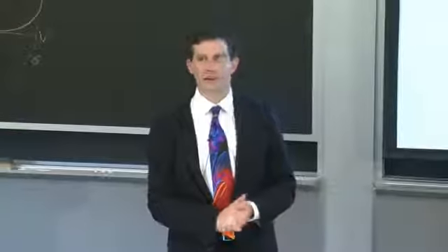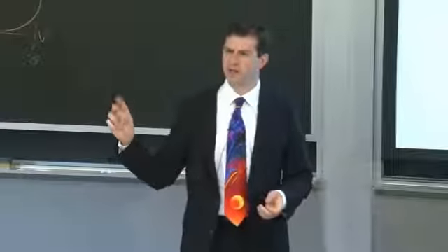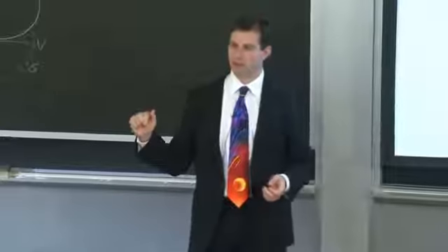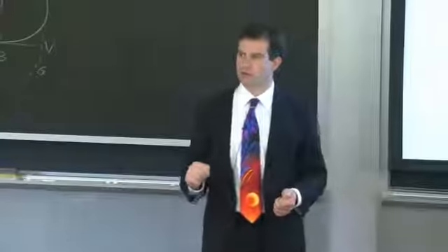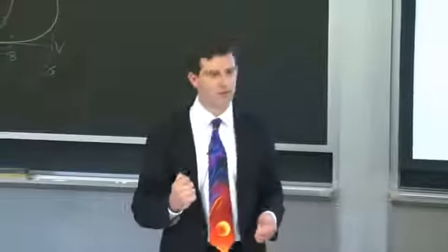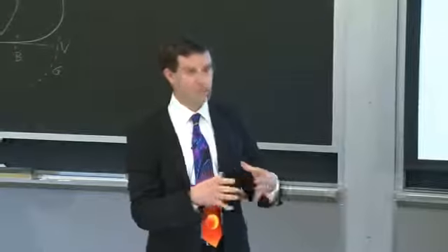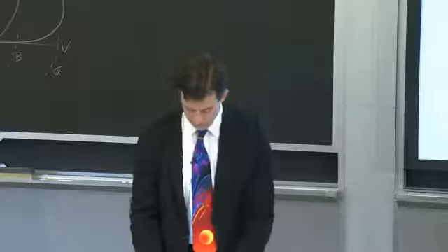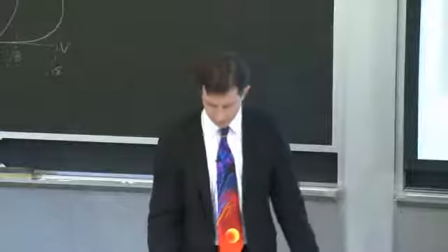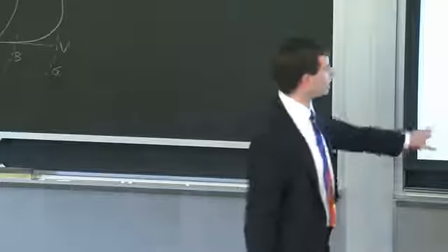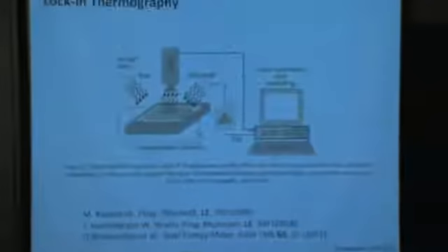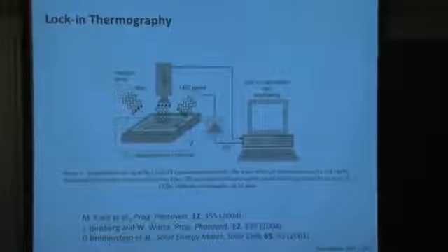And they thought about it long and hard, and they said, well, gee, these new handheld digital cameras coming out in the market are pretty cool. What technology do they rely on? Oh, it's a CCD, charge-coupled device, that images over a large area the output of a device. And that's exactly how the lock-in thermography techniques were developed, with this imaging camera. In that case, an indium antimonide CCD.